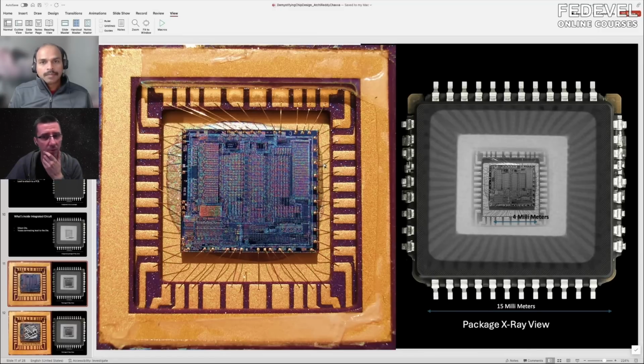I remember when I was making one video, we were talking about one of the possible problems, which was, for example, that these bond wires got disconnected because of vibrations or something. I wanted to point this out because the problem may not be only in the silicon. Sometimes if there is a faulty chip, a bond wire may even break. That is an interesting topic.